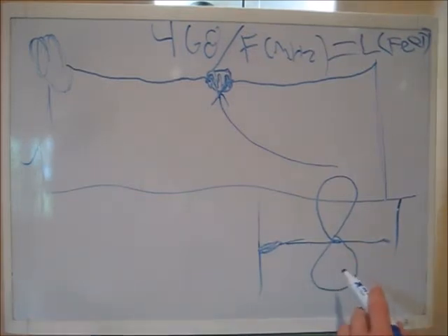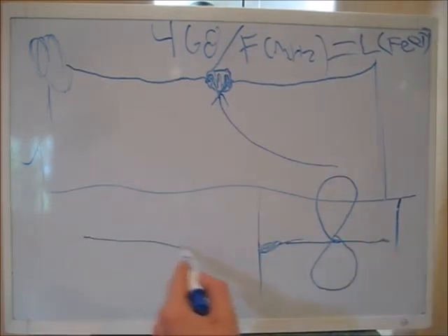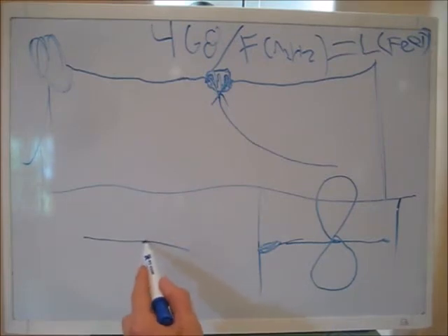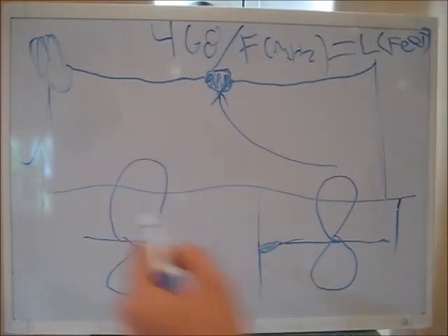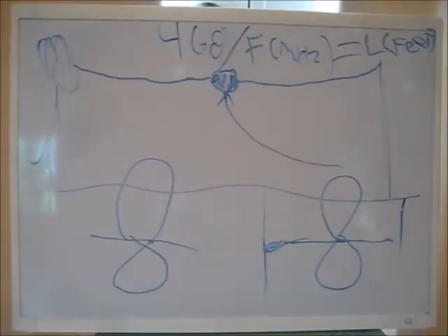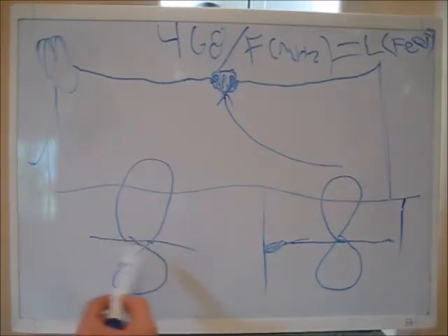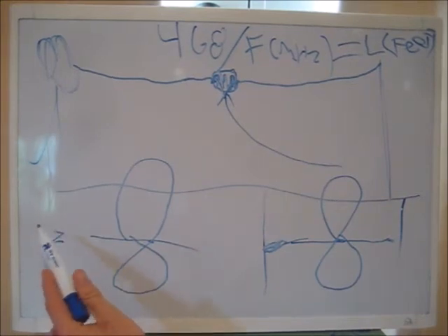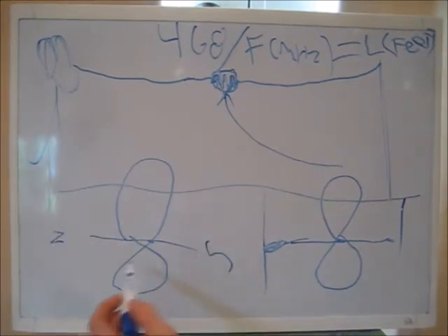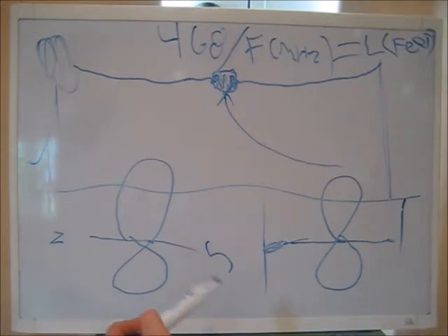Now this is a terrible drawing, so I'll do it again over here. Here's your dipole. Here's the center. It radiates something like this. Okay, a very wide figure 8 broadside to the array, which means if you have a dipole antenna up in the air and this is north and this is south, then your antenna is radiating east-west.